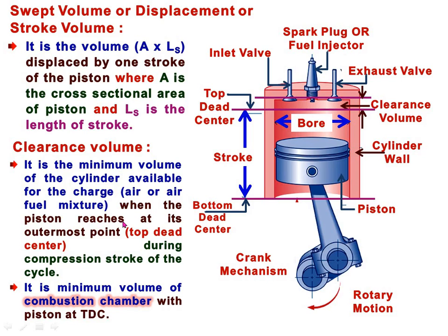In the suction stroke, the inlet valve opens and the air or air fuel mixture is introduced in the cylinder. After that, during the compression stroke, the piston travels from bottom dead center to the top dead center, and ultimately it reaches the top dead center.